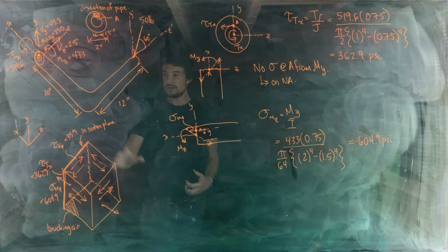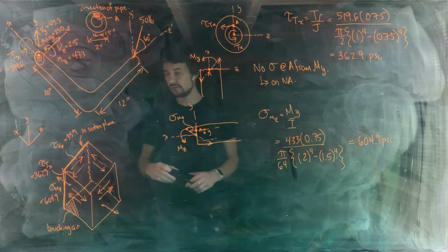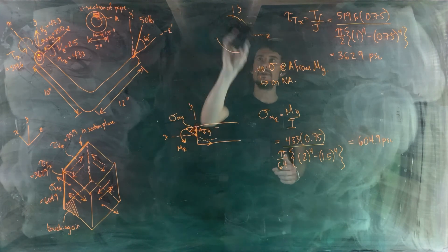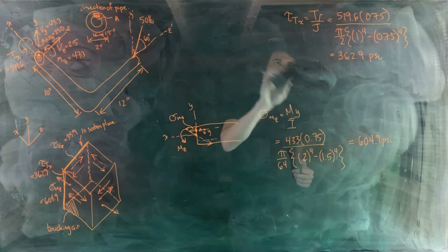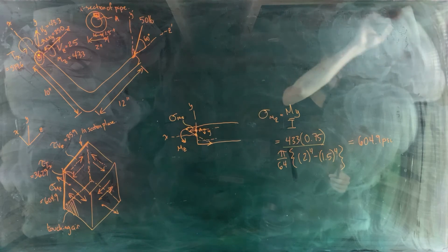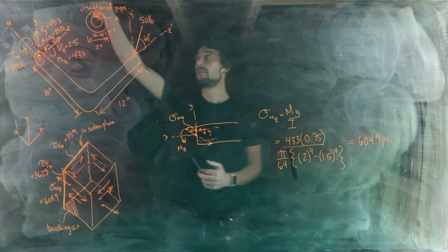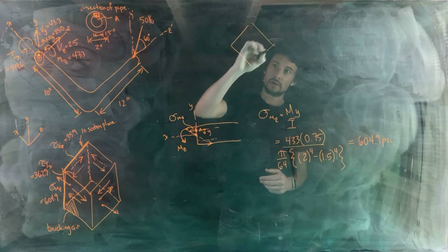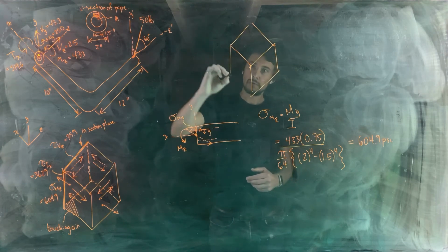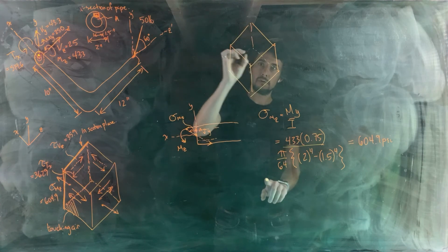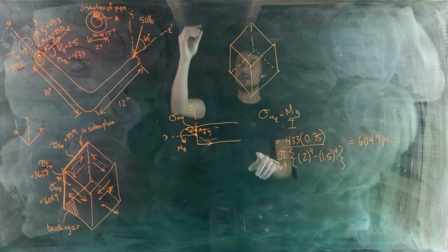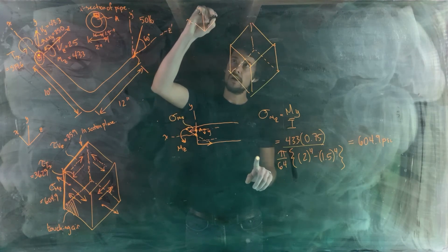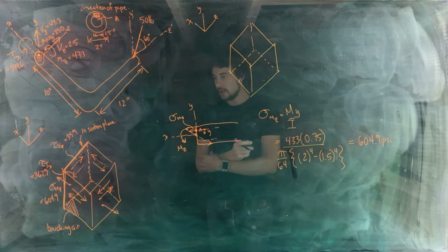Okay. So now we've made it all the way through our internal forces, torques, and moments, and we can look at this volumetric element and combine those stresses that can be combined, and then provide the sketch of our answer with the combined stresses, with the appropriate labels and magnitudes as our answer to the problem. So I'm going to re-sketch the element. There we go. And put the coordinate system in. And we had x, y, z, like that. And then let's go back to our element.